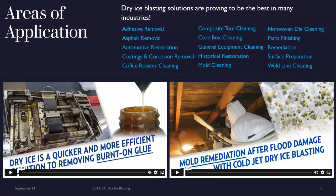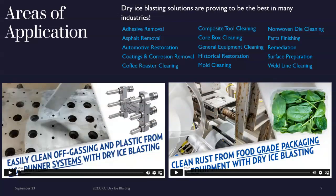Dry ice blasting is a very much more efficient and quicker way of removing burn-on glue, two-part adhesives, plastic mold packaging, mold on wood or any surface after flood damages, and fire restoration, getting the soot or the charred wood off. Dry ice blasting also is very good for any kind of food-grade packaging equipment, pulleys, rotating parts.